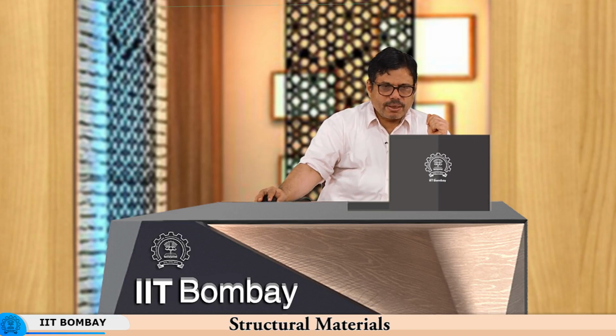Okay. Now, deformation in hardening may be substantially reduced by employing special heat treatment procedures which enable tempered martensite and an increased amount of retained austenite to be obtained after hardening. This is achieved by increasing the hardening temperature to a certain extent and by slow cooling through the temperature range of martensitic transformation. So, this is what we have seen in this slide, and this applies to all heating media.